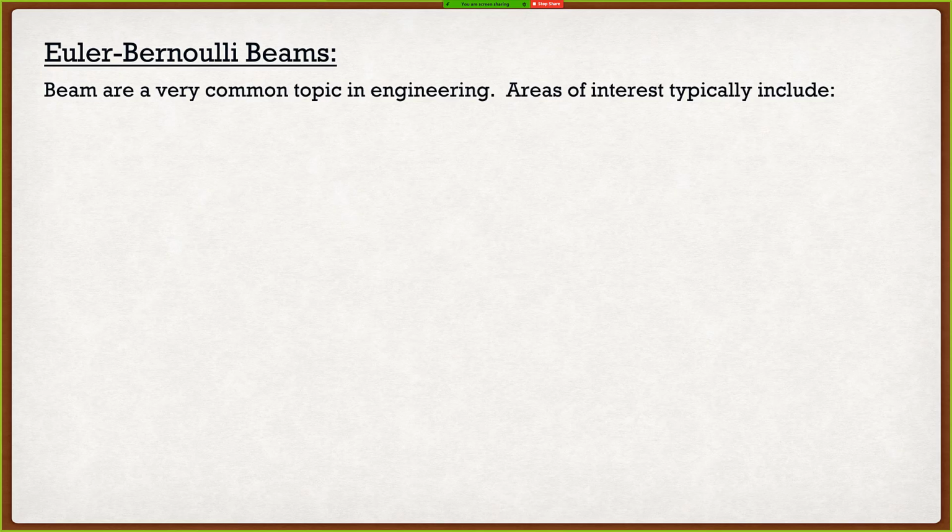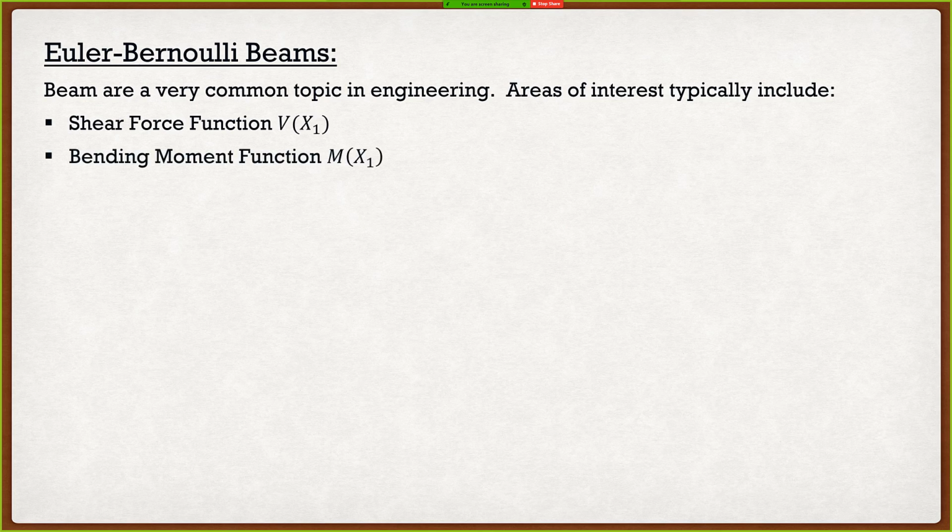Now, areas of interest in these beams can vary. Let's say I can be interested in the shear force function V. I can be interested in the bending moment function M. And typically these two are very simple. We learned them all the way back in Eng 130 or statics. Not too hard to calculate. We can get a little bit more complex though, because another thing that we need to design beams for is deflections. We need to make sure that our beam is serviceable so that the occupants don't throw up every time they walk on your floor. This one gets a little bit more complex.